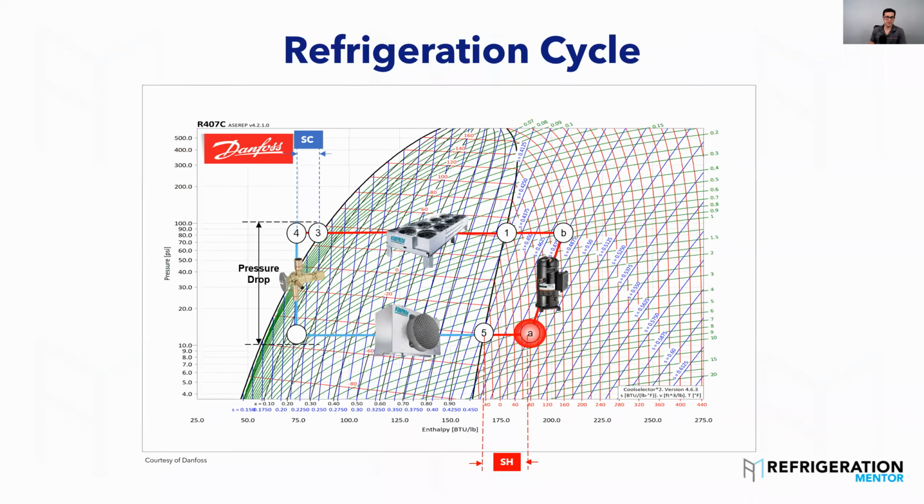Between the receiver, you're right, Brett. That droplet condensate goes back to the receiver, also known as a condensate line. A lot of people don't know this. I said this a few years ago, and people laughed at me online, but that condensate line, or drip leg as some people call it, is the only place where refrigerant will flow in both directions in a system. Out of that condenser, you have liquid dropping down into the receiver, and then you have vapor moving up from the top of the receiver back into the condenser.